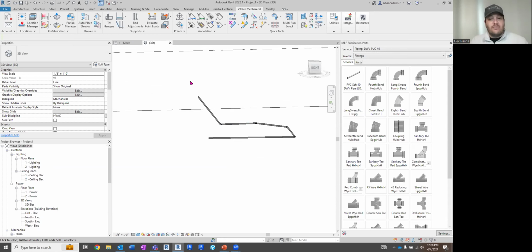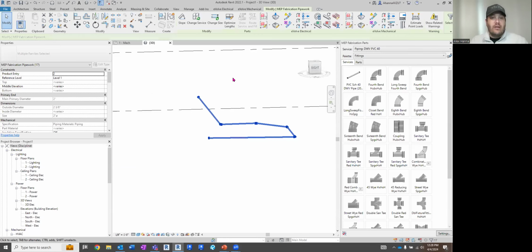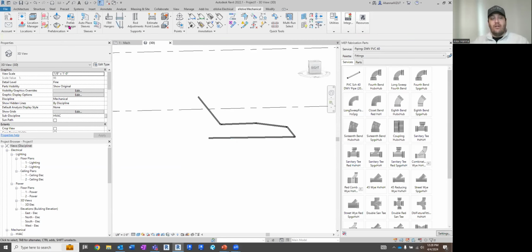The prefab manager is the spooling tool I talked about earlier. So the manual process for assemblies would be to highlight your parts and hit create assembly. With Evolve under the prefab manager, once an assembly is created, you can generate sheets, you can generate plan views, you can tag all these items specifically to your needs. And so now your spool drawings are set to hand out. So is your plan set with all of your spools on it, the spool map. And all you really had to work on was concerning yourself with how well your model is built.